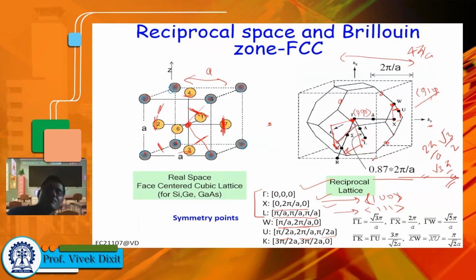Ideally we have to calculate the E-k diagram for all the k vectors, but there will be an infinite number of k vectors, right? So we cannot draw E-k for all of them. It will be difficult to visualize. So what is done? We draw this E-k diagram for definite symmetry points, especially 100 and 111, right? Then we can represent it using a 2D diagram.